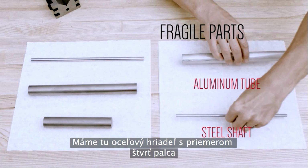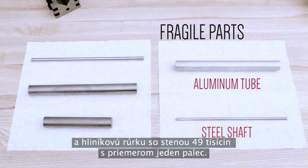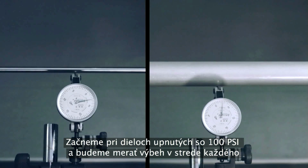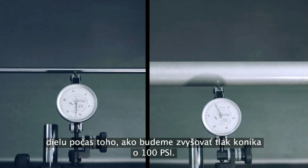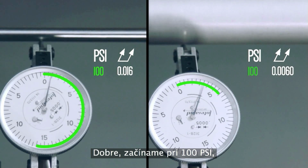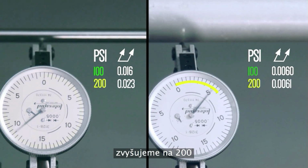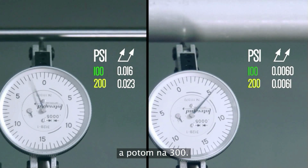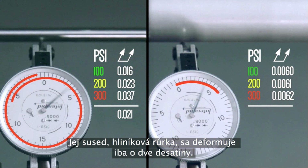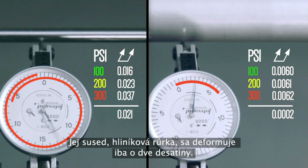Here we have a 1/4 inch diameter steel shaft and a 49 thou wall 1 inch diameter aluminum tube. How much pressure will it take to deform them? Starting with the parts held at 100 psi, we'll measure runout at the middle of each part as we make 100 psi tailstock pressure increases. Okay, starting at 100 psi, increasing to 200, and then 300, the steel rod deforms significantly by an additional 21 thou. Its neighbor, the aluminum tube, deforms by only 2/10.